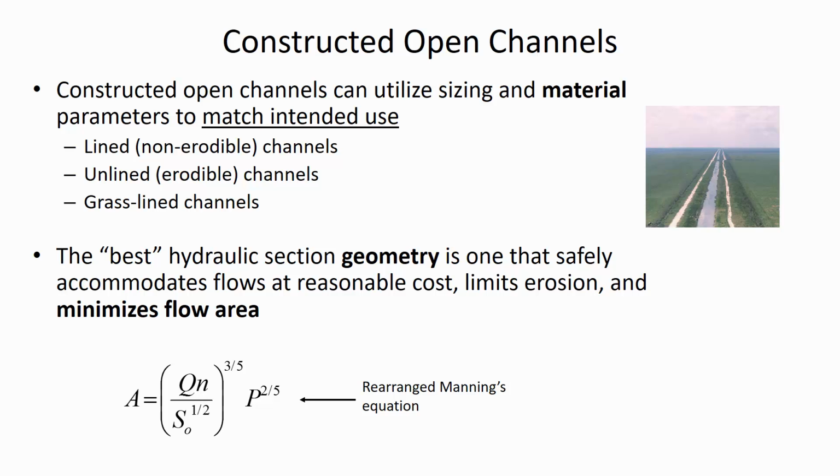Here in Huntington, they've started to adopt stormwater ordinances that require new construction to trap water underground. The new practice facility is an example where they have some underground water storage under the parking lot. If you look at the parking lot at Cookout, they've got asphalt there that is pervious pavement. It's not real durable and doesn't hold up well, but it does promote infiltration. So those are some ways to shape upstream how much flow is going to have to be accommodated.